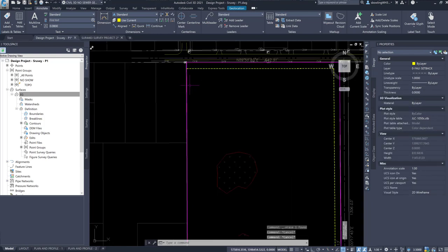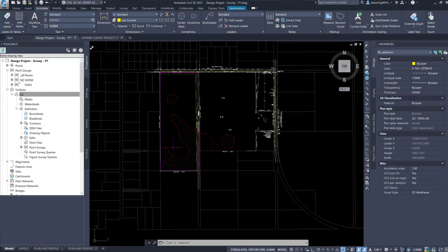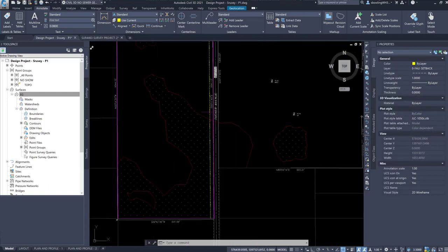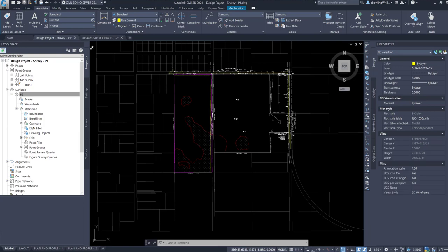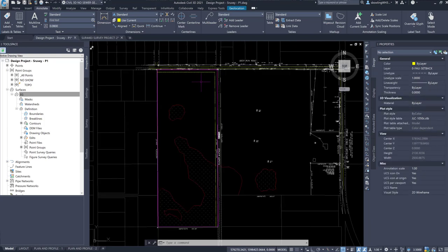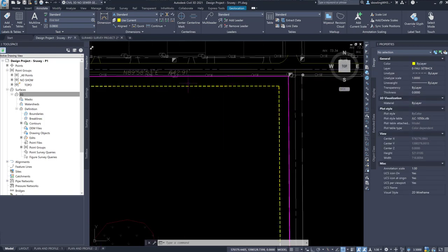And the reason I change my mind is because it's going to be the same land use. This is residential and this is residential. All right? But usually you have a front setback for some type of landscaping features. Now, you have two access points. You'll either build this road down to here for Tucker, or you're going to come in off of Deer Run, okay?